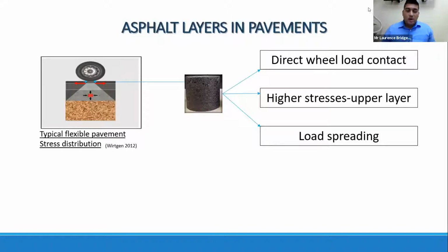Notably, in the upper sections of the pavement, particularly in the zone of contact between the load and the structure, the contact area for these imposed stresses is relatively small. As such, the upper pavement layers are subjected to higher stresses and strains, and as a result need to have durability as well as strength properties to withstand these enhanced stresses and strains.